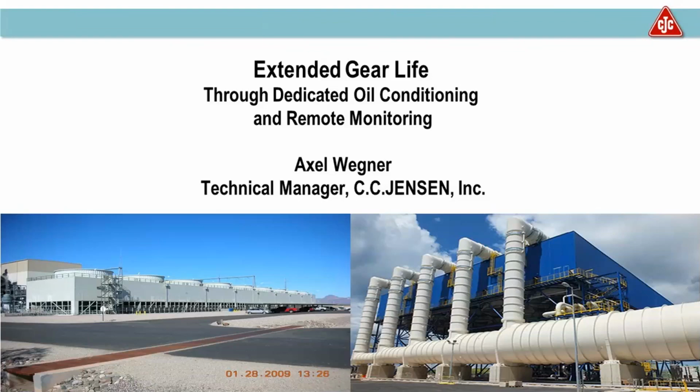Yes, thank you. So this is not specifically directed to Axel, but I wanted to know what is typically a good duration in terms of running hours for a new gearbox to reach that point where the gears have been run in, so that you can determine if your gear wear is unacceptably high.